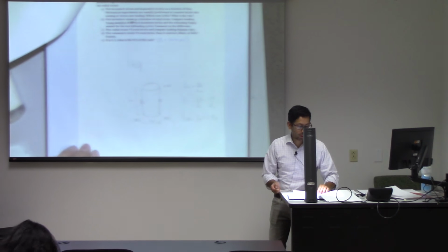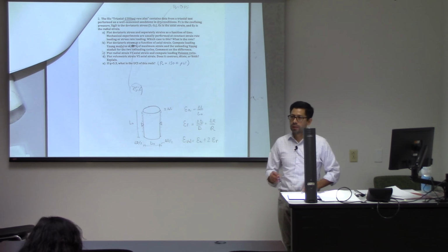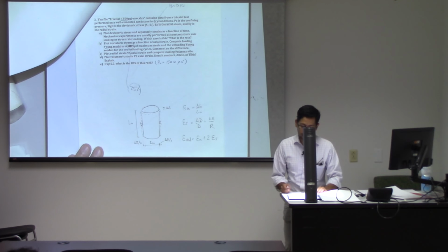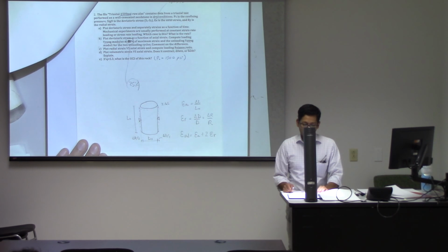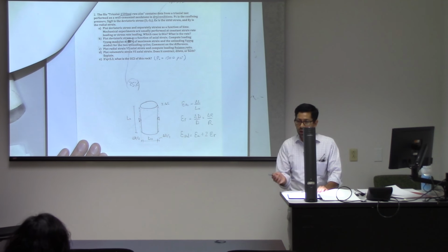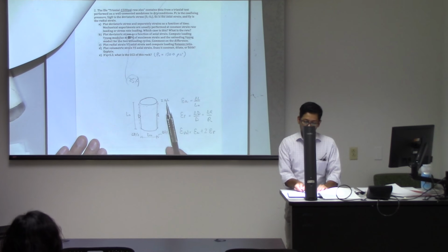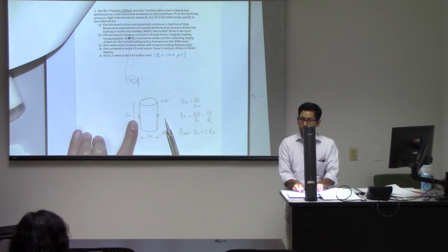And the next point is with the triaxial test to compute Young modulus and to compute Poisson ratio, and also to look at volumetric strain. So let's see what is going on. I gave you data for a real test that we did in the lab, in which in addition to S1 and S3, we measured the shortening of the sample and the widening of the sample, right?